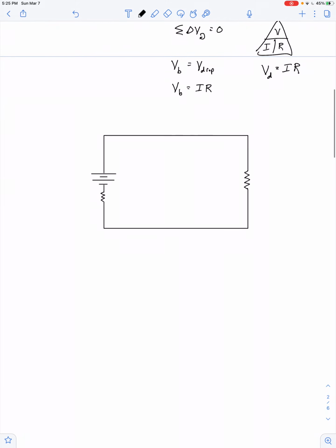If you've ever taken a battery out of an appliance that's been running for a while, if you hold that battery in your hand, you've probably noticed it's a little bit warm. See, the battery itself wastes electrical energy and converts it to thermal energy. And one way to say that is to say that the battery itself has some amount of internal resistance, right? So we'll symbolize that with lowercase r. Now there's the capital R for the external resistance of the circuit, which includes the appliance plus the connecting wires.